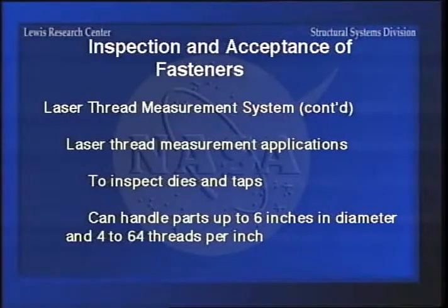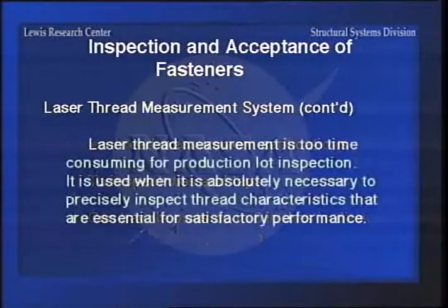Now, it's a time-consuming thing, so the places that you would use it, say, you don't have very many bolts holding an engine on a plane. So on a 747, if you wanted to inspect the super high-strength alloy steel bolts that are holding it on, you would run them through an inspection procedure like this, check every one of them, because there it's a super critical application.